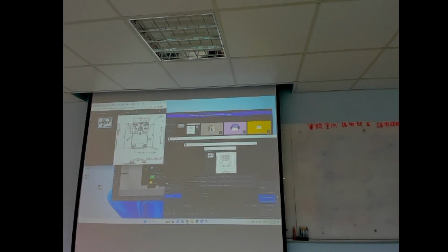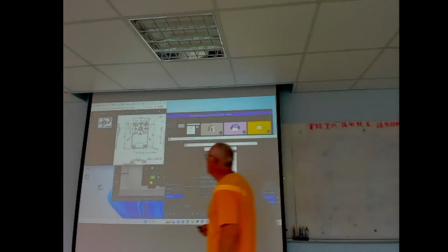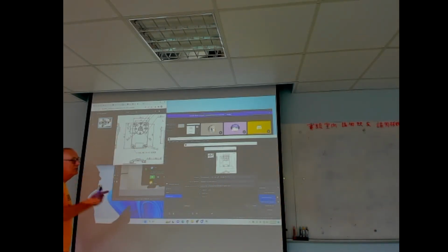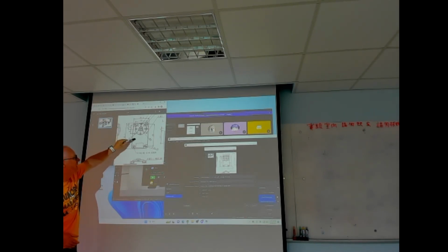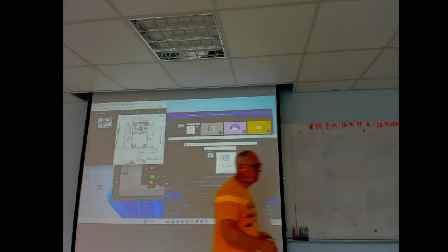So to get from our inertial frame to our first joint would be a translation only. I don't need to do any rotation. The z-axis is already in the correct direction. And x would be negative 11.25 millimeters, and z would be the height of the servo, which is